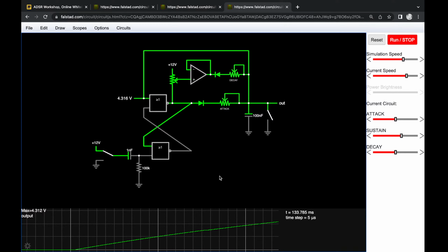And as we can see, since the voltage down here is 12 volts and the voltage up here is also 12 volts, the output of the buffer is also going to be 12 volts. So whenever we're in the attack phase, this node here will sit at 12 volts simply because this is high. So that's what I meant earlier. That's why it's important that this voltage divider always gives us 12 volts whenever we're in the attack phase, because now no current can flow into the buffer simply because the voltage on this side is higher than the voltage on this side, right?